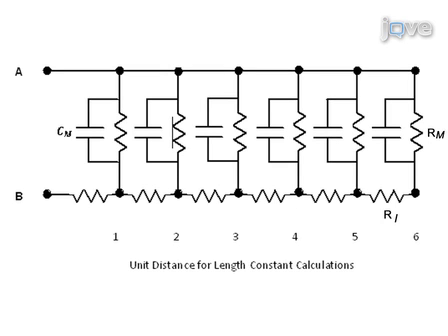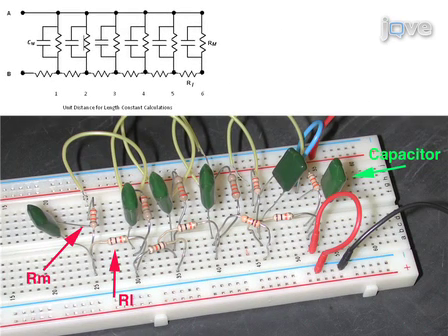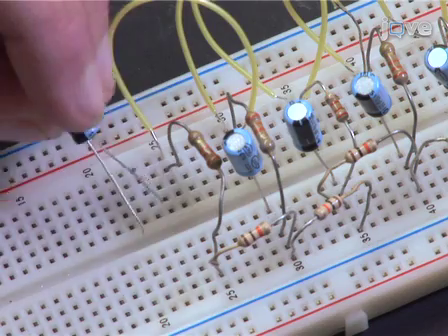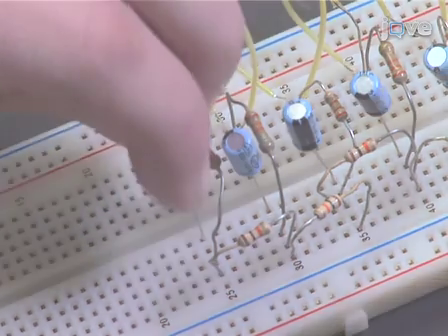In order to better simulate the passive cable properties of nerve and muscle fibers, the model nerve cell will be expanded to contain both resistive and capacitative components. Not only is there a transverse membrane resistance present in the nerve cell membrane, there is also a surface membrane capacitance, which distorts the nerve cell signal. To simulate this, attach 10 microfarad capacitors in parallel to the transverse membrane resistors on the breadboard.